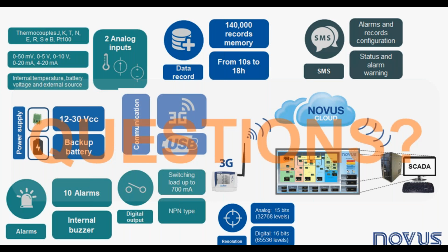Another question here. Can the digital input receive pulses? Yes. Lockbox 3G has one digital input. It can be configured to read the digital information or to configure as a pulse counter. So yes, we can receive pulses on it.